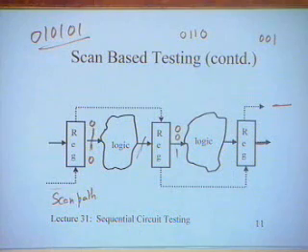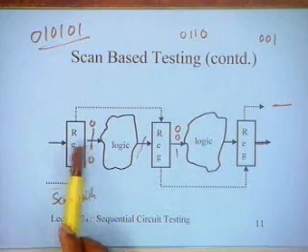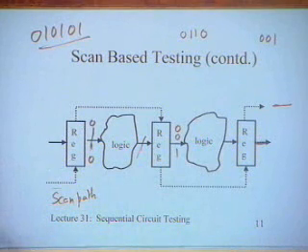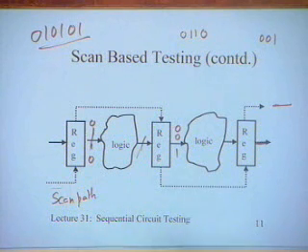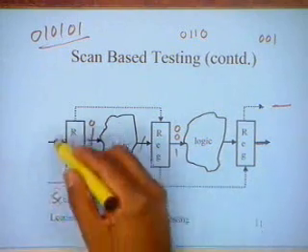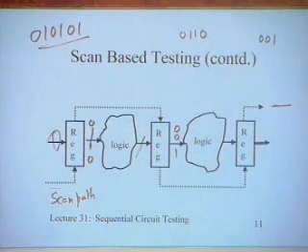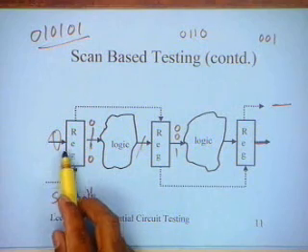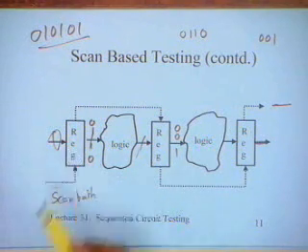Apart from that, when you are testing the flip-flop, you are not using the same path as the path that is used for the functioning of the circuit. So you actually have created another path. So the flip-flop may show that it is going 0 and 1, because the flip-flop logic inside can toggle, but there is a problem at the input over here. That's not going to be tested, at least not in this mode. If all your test patterns happen to take a value 0 on a particular output, then that flip-flop is not going to get tested.